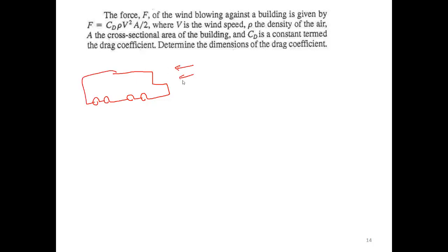Anyway, there's a drag force or resistance here, and when they work with a fluid, they put it in terms of a coefficient called C sub d, which is the drag coefficient, times other fluid properties, which are half rho v square times the area, or as they have arranged it here, rho v square times A, all of it over A. But basically that's the kinetic pressure here, half rho v square.